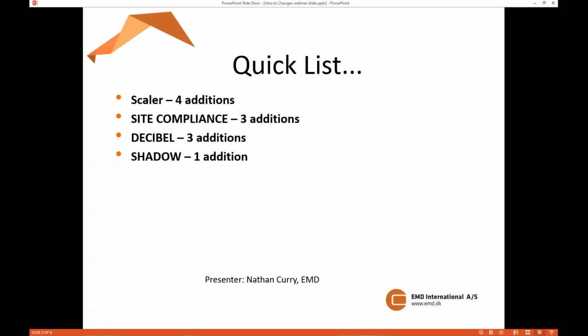So moving on to decibel, there's now flexible coloring of NSAs. We've updated several of the country-specific models, and you can now calculate topographic screening effects. Now, this is not part of the ISO standard. It has been devised for the UK market, but we've made it available for all markets when choosing fixed ground attenuation.